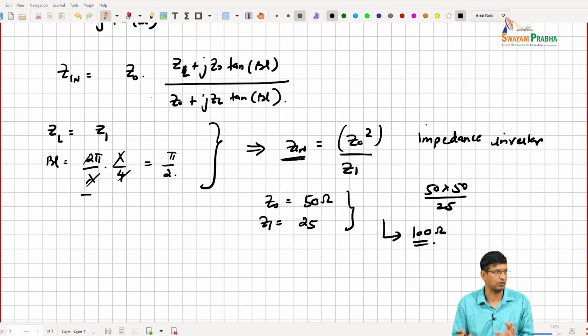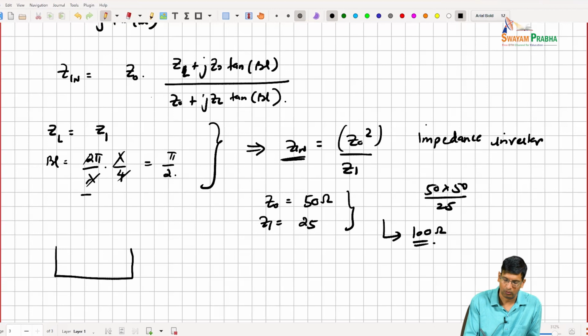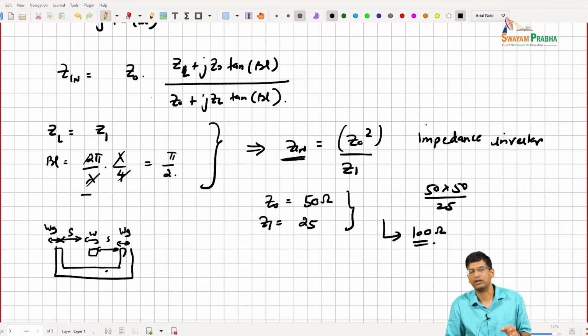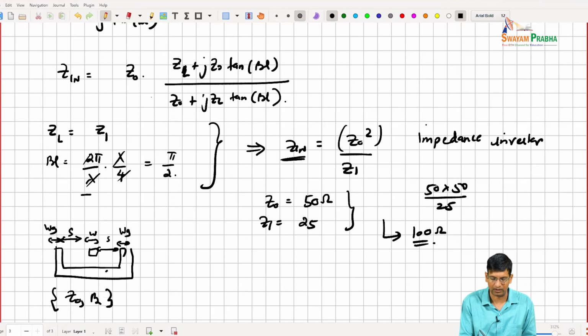in your design, because once you have developed a transmission line structure where you know what width you're using and what spacing you're using, and let's call this the width of the ground, right? So once you know these details about your transmission line, you can design your circuits, just assuming that you will be able to get the Z0 and beta that you target, right?